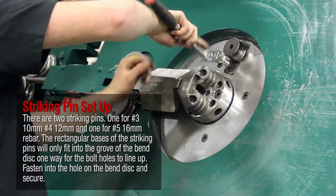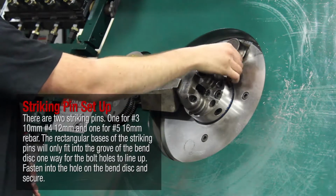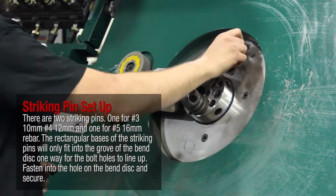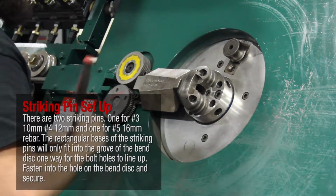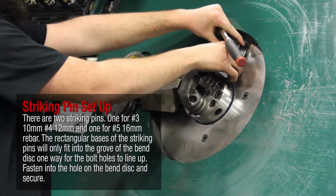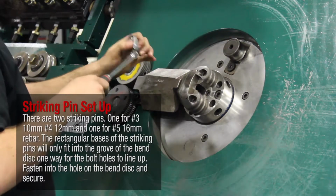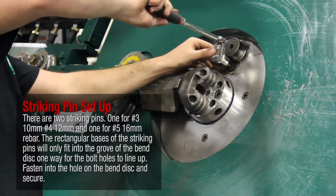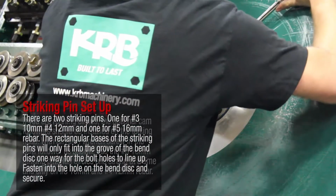Striking Pin Setup. There are 2 striking pins. One for number 3 10mm, number 4 12mm, and one for number 5 16mm rebar. The rectangular bases of the striking pins will only fit into the groove of the bend disc one way for the bolt holes to line up. Fasten into the hole on the bend disc and secure.